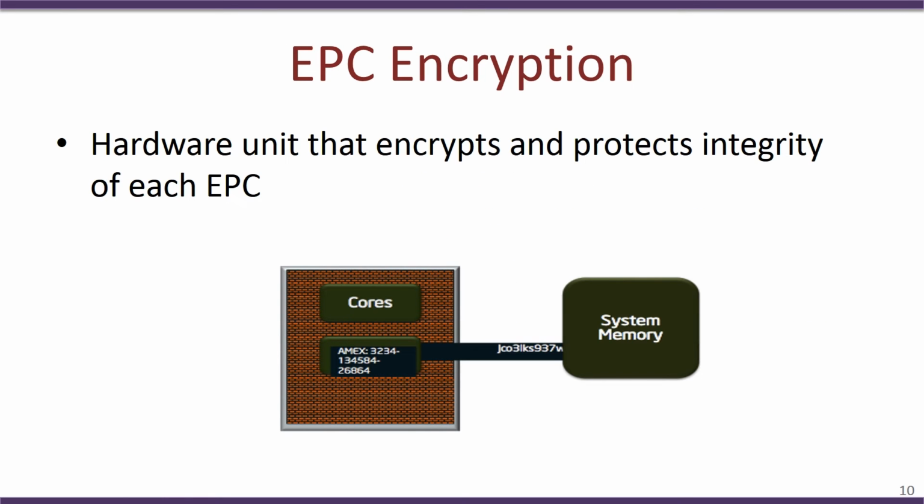As we mentioned, one of the distinctive features of the SGX mechanism compared to the ARM TrustZone is that SGX supports encrypted memory. So, if we consider this as our processor with the multiple cores and so on, and we assume that this is a hardware enabled processor, then any data which is sent out of the processor or received from the processor is in an encrypted state.